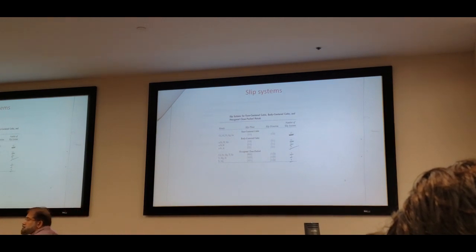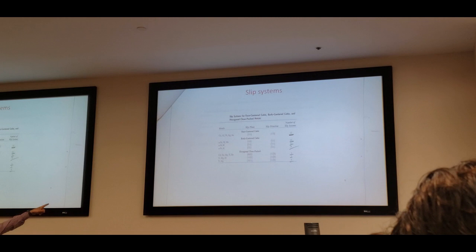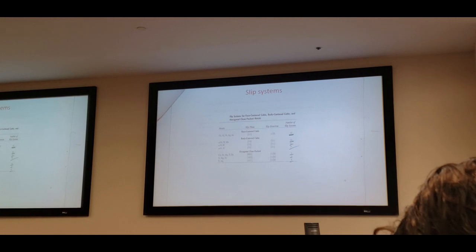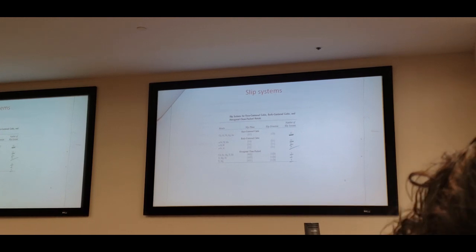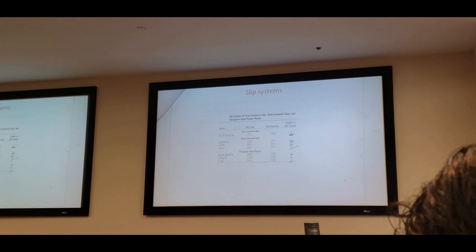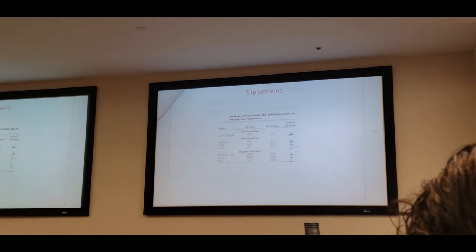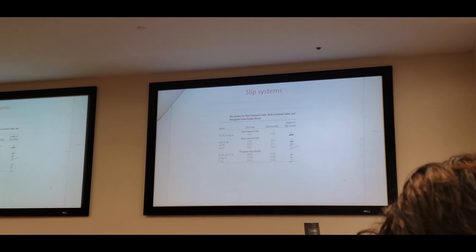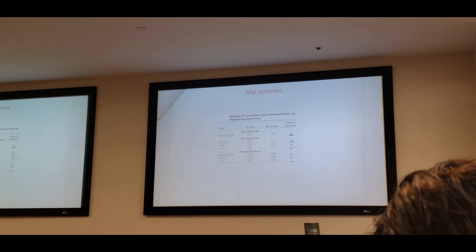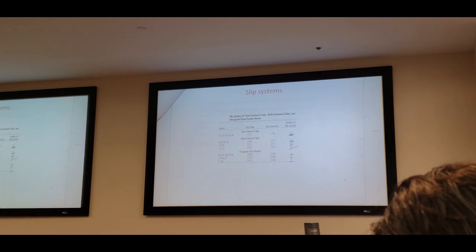Yes. So that means the only way that BCC is greater than FCC is for a given material. For that given material, anything else would be equivalent, because they'd be exactly the same, 12. Again, there are other factors too. It is not completely this one. There are other factors, depending on the strength of the bonds and others. But considering everything else the same, that's what I'm asking. If you compare these things, the FCC is more ductile than the HCP structure.